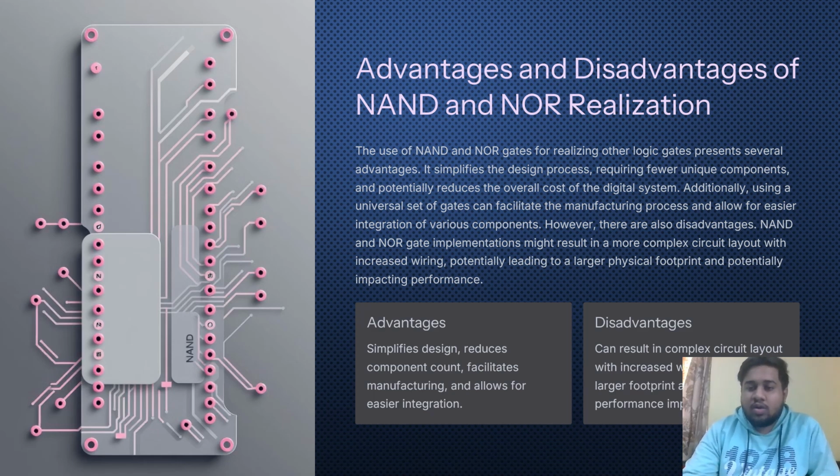However, there are also disadvantages. NAND and NOR gate implementation might result in a more complex circuit layout with increased wiring, potentially leading to a larger physical footprint and potentially impacting performance. Advantages: simplifies design, reduces component count, facilitates manufacturing, and allows for easier integration. Disadvantages: can result in complex circuit layout with increased wiring, leading to a large footprint and potential performance impact.